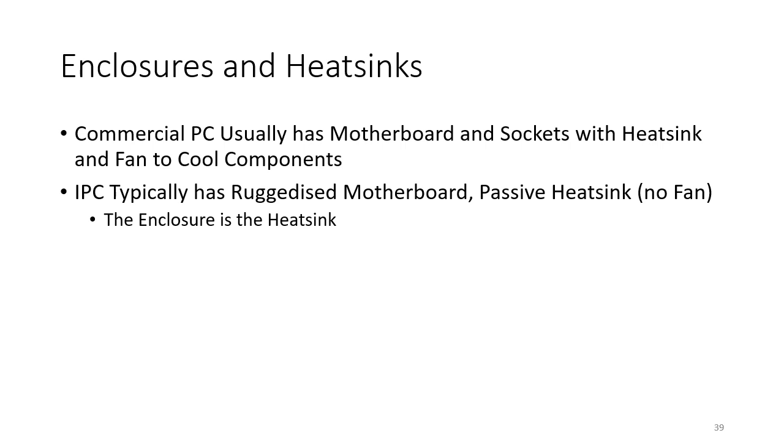With an IPC, these are typically much more ruggedized. So you'd have a ruggedized motherboard, often a passive heatsink, so there's no fans. And in many IPCs I've seen recently, the technology is designed so that the enclosure also acts as the heatsink. So what you typically have is a steel, or more likely an aluminium enclosure. The aluminium enclosure is tightly bolted to the motherboard, along with heat spreader and other technologies which get the heat from the chips and put it out into the enclosure. And then the enclosure would have vanes on, and what you're relying on is ambient airflow to take the heat away by flowing over the vanes of the actual enclosure itself.